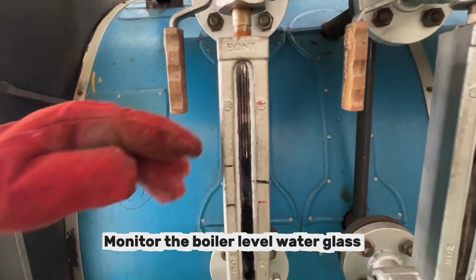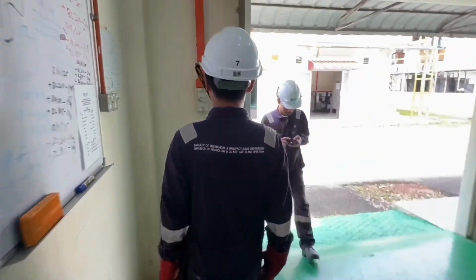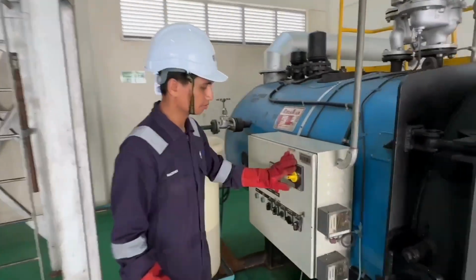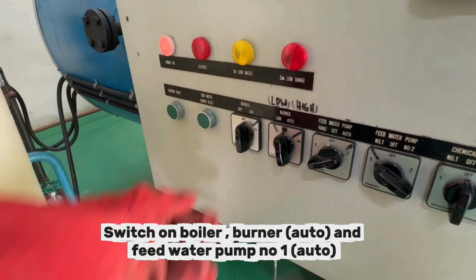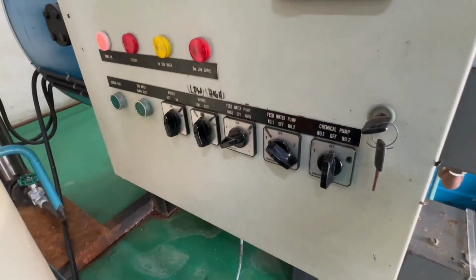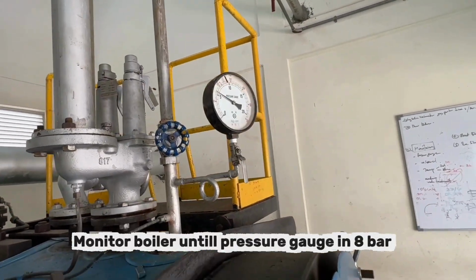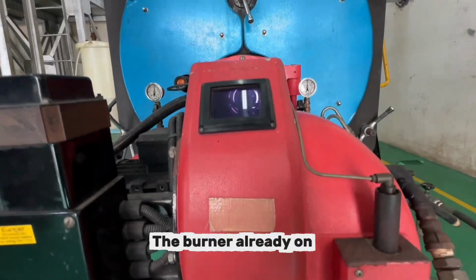Monitor the boiler level water glass. Switch on the main power supply of the boiler. Switch on the boiler, burner auto, and feed water pump number 1 auto. Monitor the boiler until the pressure gauge reaches 8 bar. The burner is already on.